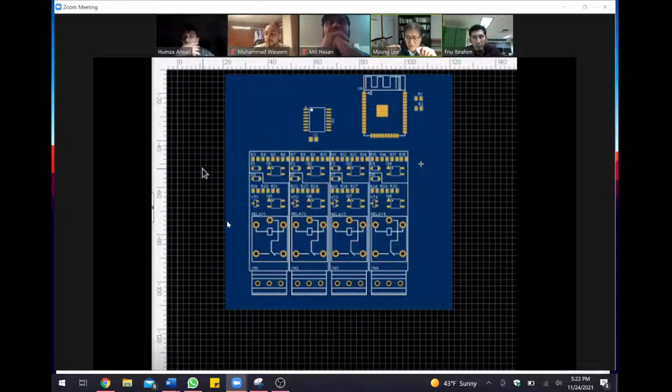Otherwise, this one generates noise. I mean, it is no secret that the relay is on and off, right? It's controlled by the galvanic part. Because it's a high voltage on and off, that might generate a spark, which impacts the other circuit, which is operating at like 3 volts.